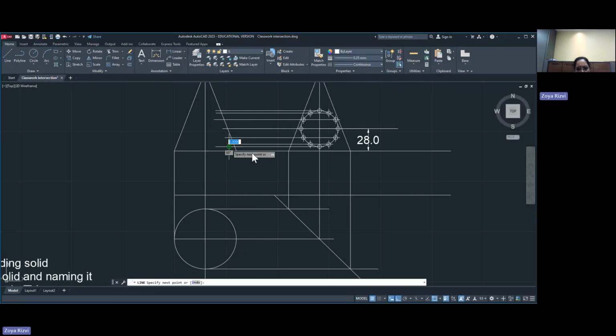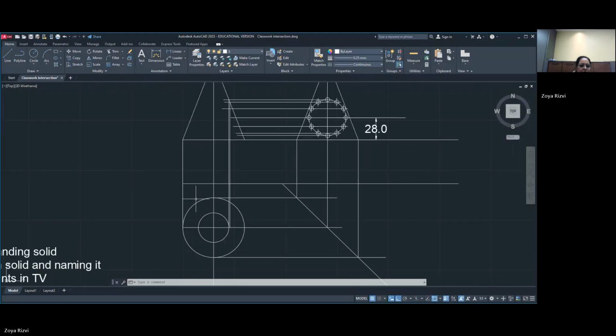This is the last point. Now dropping these points below. This is the very first circle. So you get that in the top view, you are able to locate this circle from locating these points. And the next circle will be next to it. The next circle will be drawn similarly by dropping these points on the center line.